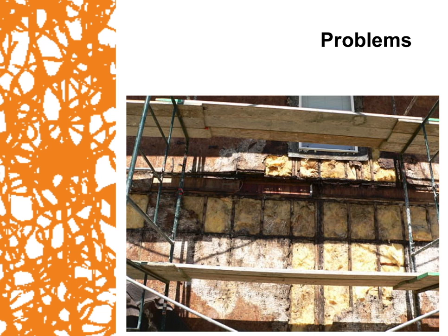This is what's occurring behind our facades, and this is what they're hiding. Again, they hide it very well until the point at which you notice it, and then it's too late. Then you come to this type of problem where you not only have a moisture problem, but you no longer have sheathing material or potentially even framing members that are complete.